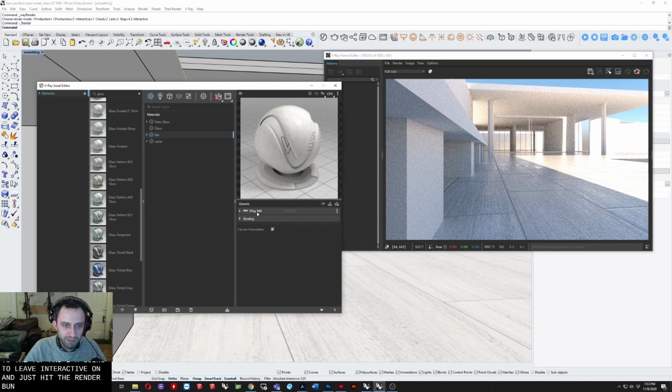You're typically going to have, for the best materials, several layers. I think the minimums are that you're going to have a diffuse of some sort. You're going to have something that defines the glossiness, which is what we added in, not in refraction, but in reflection. And you're going to have a bump map that defines the three-dimensional quality to this. I actually, looking at this, think we could even take that down just a little bit more. Let's try 3.